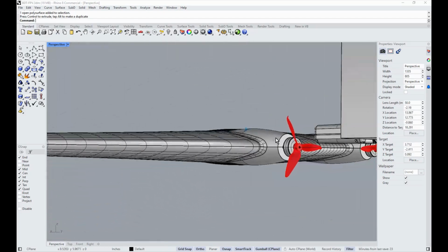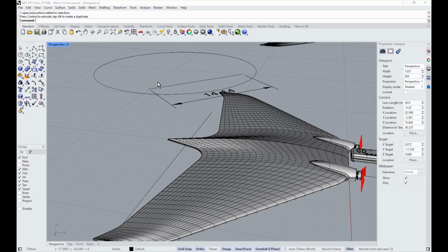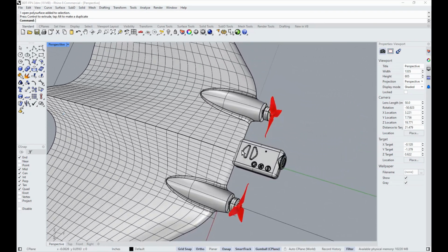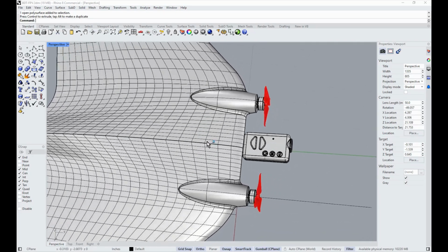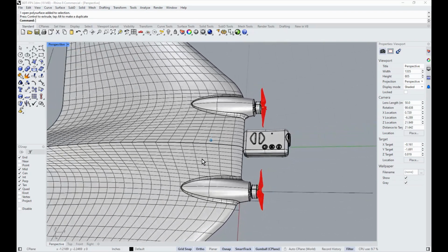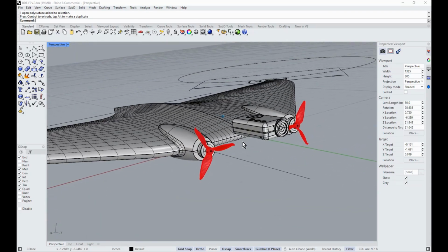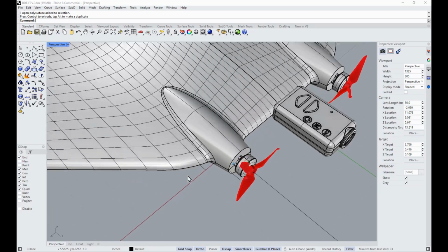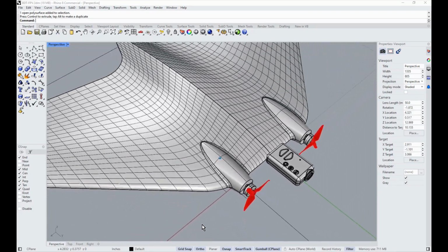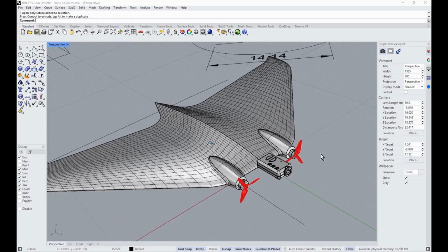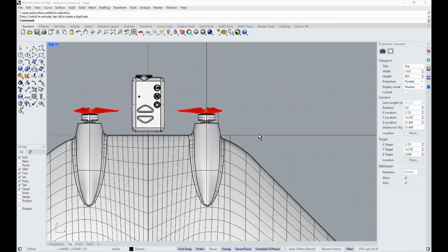There's a lot of volume in here, even though it's a small aircraft. It is going to have a small vertical stabilizer. Really no need for a rudder because you've got twin engines in a conventional twin setup, so use differential thrust programmed into the transmitter. But the next piece of the puzzle is in CAD figuring out where these pieces should go to get this thing balanced. As you can see, it has a lot of compound curves, so this is really set up to be 3D printed in sections. So that's basically the overview.